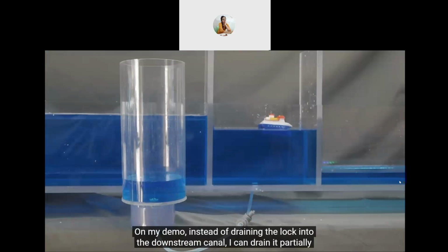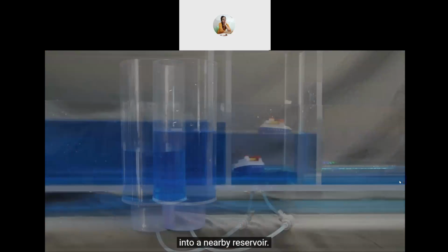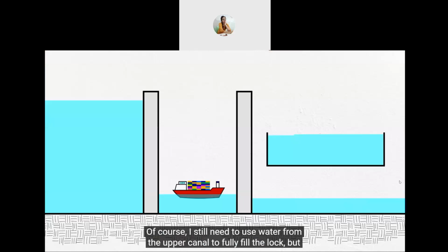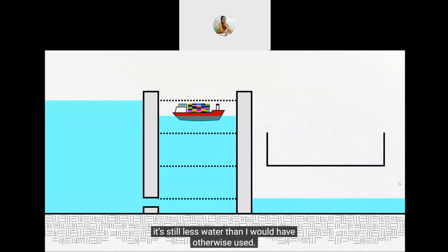On my demo, instead of draining the lock into the downstream canal, I can drain it partially into a nearby reservoir. Then, when the time comes to fill the lock, I can recycle the water from the basin, also called a side pond, to partially raise the level. Of course, I still need to use water from the upper canal to fully fill the lock, but it's less water than I would have used otherwise.